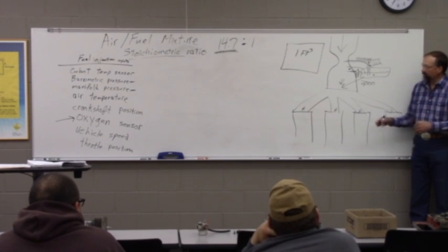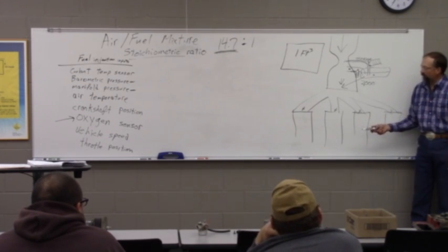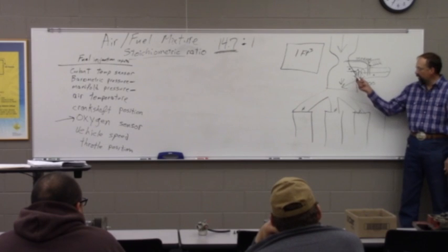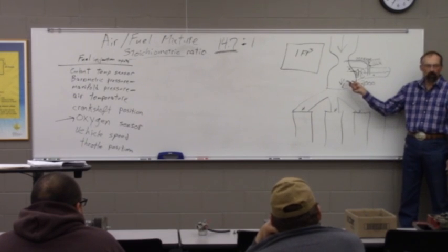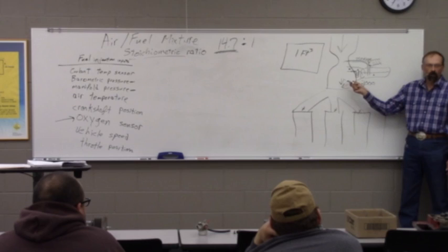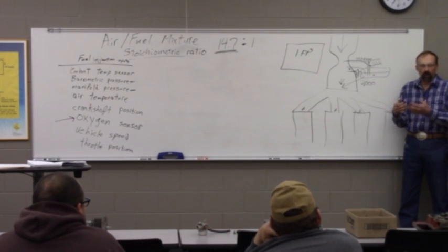Then the next advancement was, so in the early systems, this throttle body injector, it sprayed all the time. Now there was a lot of controls that controlled the pressure and whether the valving in it was wide open or restricted, and so it controlled the amount of fuel, but it sprayed all the time.